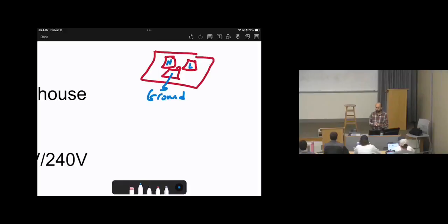So we have a protection tool that will detect if there is a current flowing into the ground, then the circuit breaker will trip. This means in the normal situation, there must not be any current flowing to the ground. If there is any current flowing to the ground, then definitely there is an electrical system problem in your home. Then the circuit breaker will trip to prevent fires.